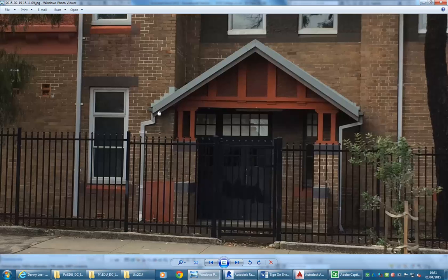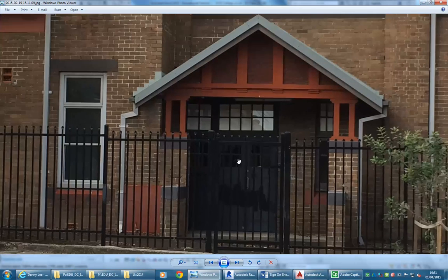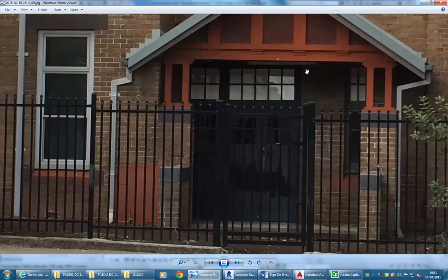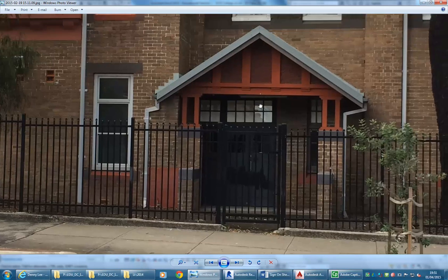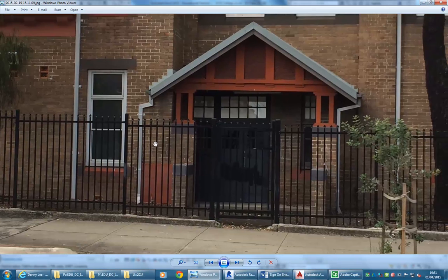It's probably best to make them first before attempting the doors and the other openings that you have inside there. If you can though, I'd be looking at making that door family. If you haven't made it, just start with a door that's similar. This would be basically a double door with a panel to the left that's probably fixed, and then you've got the fan lights above. If you can't find anything else, just use one of the basic double doors, and then you can try and modify that family as you work with it. But wait until you've done that porch area.